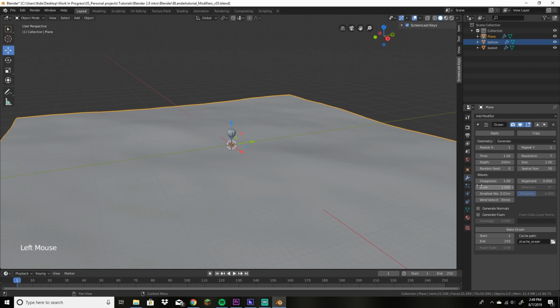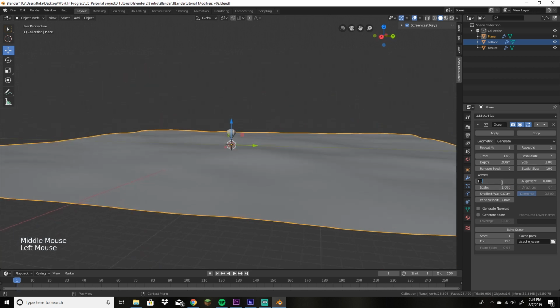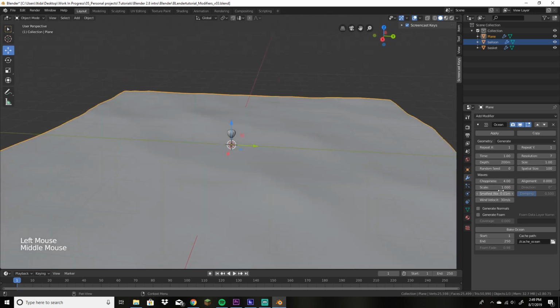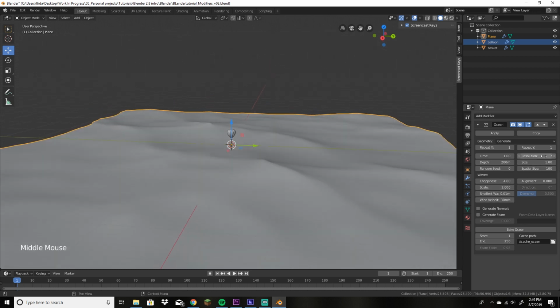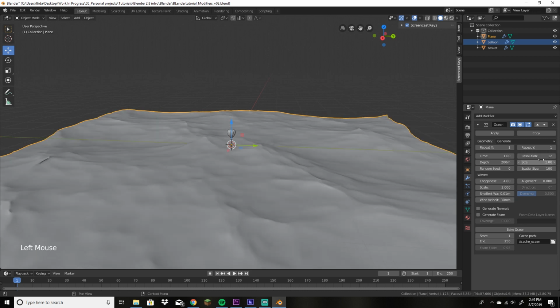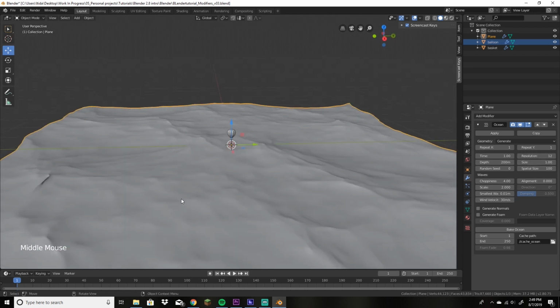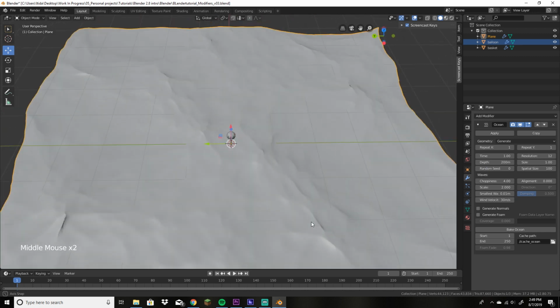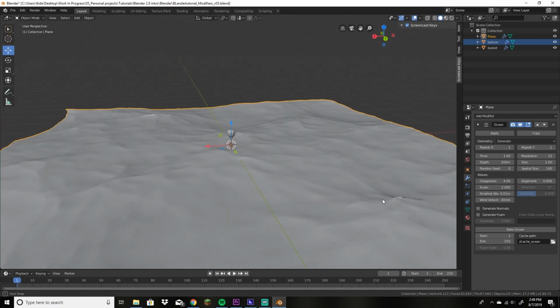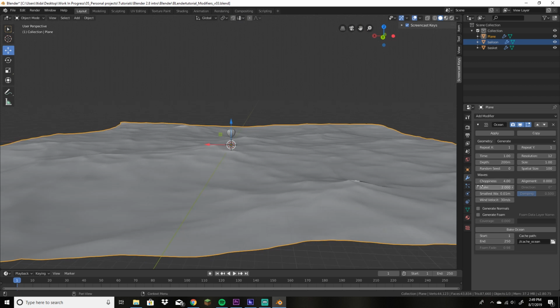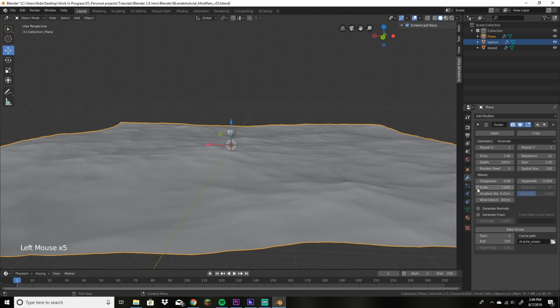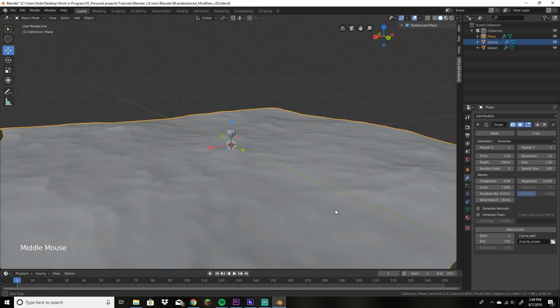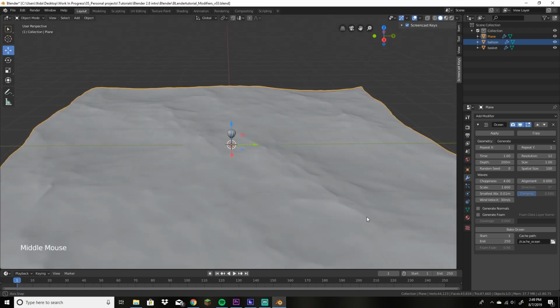I'd like to increase the size to 2, or the spatial size to 100. So double the size. And then choppiness to 4, and then scale. Well, we'll be able to see better once our resolution is up. Our resolution should be at 12. So that gives us a pretty decent ocean to get started with. Yeah, we're getting a little bit of piercing here, so you can just nudge the scale down until that stops. And I think to me that looks pretty good.